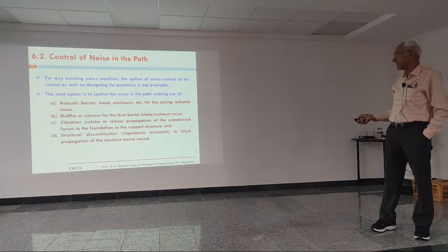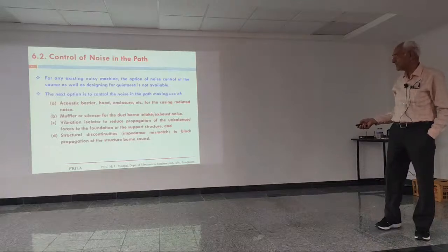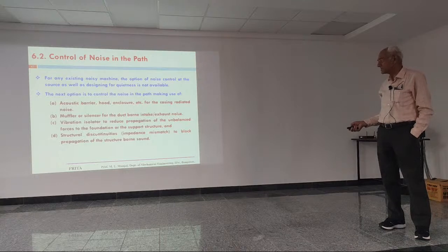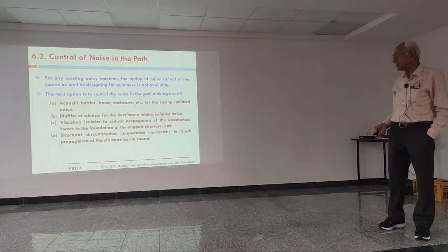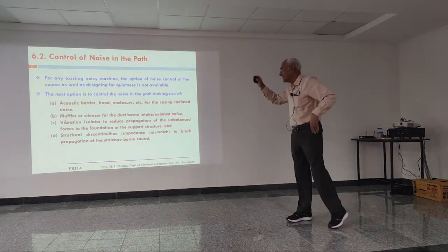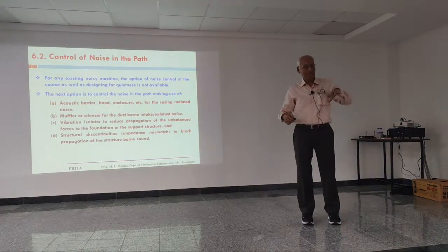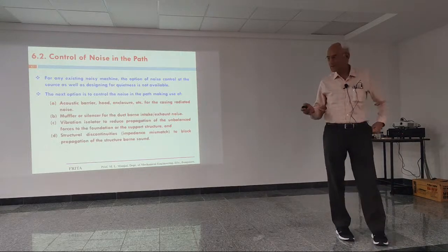etc. for the casing-related noise, and mufflers or silencers for the intake and exhaust noise, vibration isolators to reduce propagation of the unbalanced forces to the foundation or support structure, and finally structural discontinuities or impedance mismatch to block propagation of the structure-borne noise. I'm just giving you titles; there is a separate book on each of these.